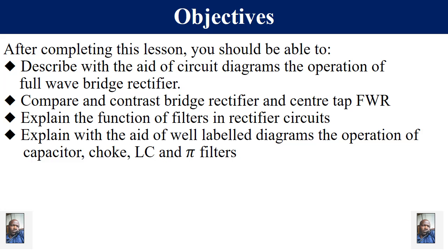Then you must be able to compare and contrast the full-wave bridge rectifier and the center tap full-wave rectifier. Then you must be able to explain the function of filters in rectifier circuits, because normally the output of a rectifier is pulsating. To remove those pulsations or ripples, we use filters. Last but not least, you must be able to explain, with the aid of well-labeled diagrams, the operation of the capacitive input filter, choke input filter, LC filters, and pi filters.